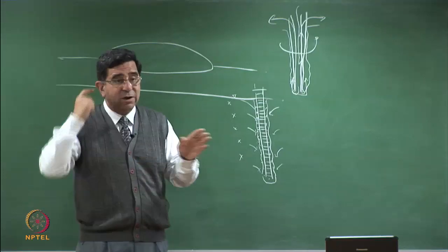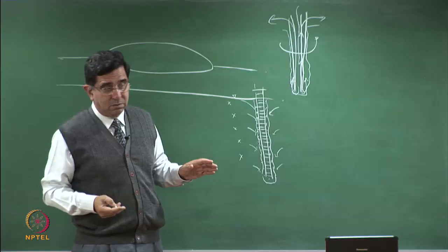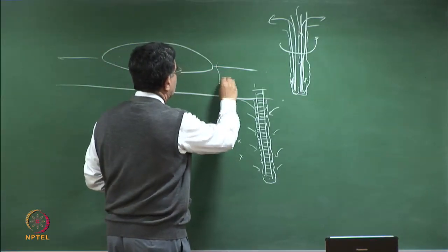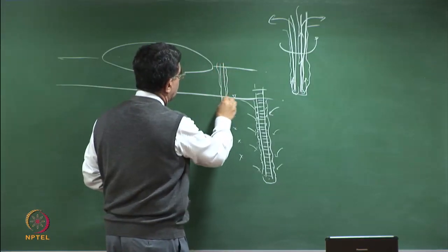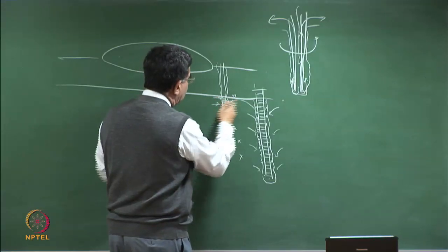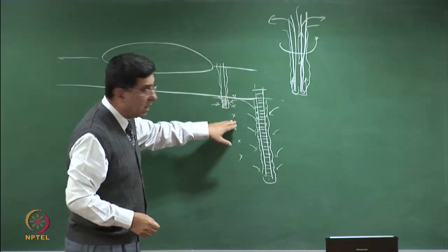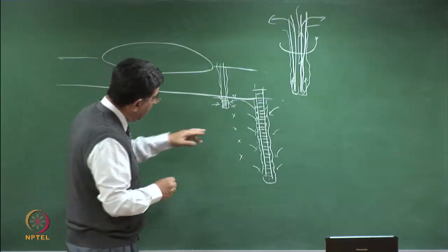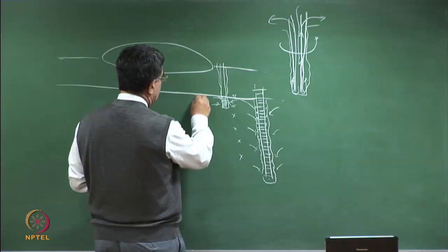To do that, either I can use a well cluster of 5 wells. So then I'll put one well up to this point and just have the screen here, so that the water which comes here, whenever I sample, comes only from this zone. And then I'll put another well which is away from this here, so that the two things don't get interconnected. And when I put the sampling here, please note, I want to do sampling here.